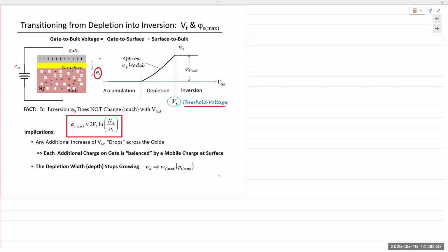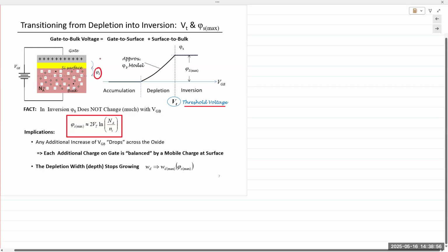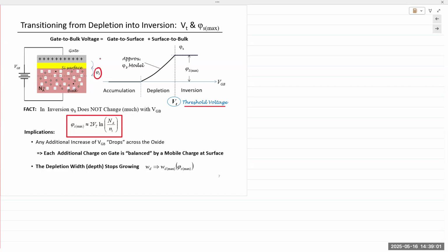Okay, that voltage is similar to a diode voltage drop. Diode voltage drop is required in order for the diode to begin conducting. It's about 0.6 to 0.7 volts. This voltage, the threshold voltage, is typically far smaller. In modern devices, it's far smaller, less than half of 0.6, so close to 0.3 or so. But again, depending on the design and the fabrication, you can have threshold voltages from a fraction of volts to multiples.